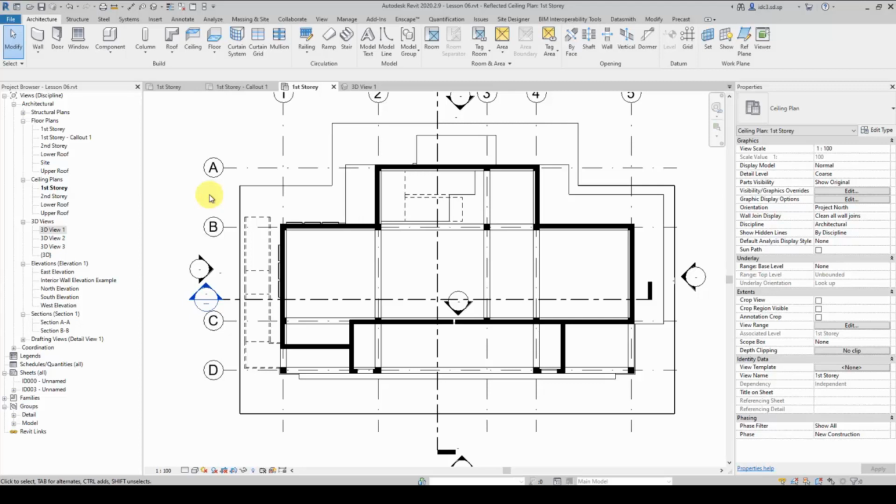Even when we change it to hidden line, it doesn't appear. It's lost. But when we change this one to a wireframe, it seems to appear. Then when I select this in plan, it is in fact placed at the lower roof, which is actually 2 levels up already. So how do we know where exactly it went?